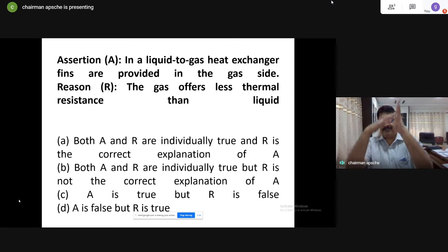When water is coming down from the top header to the bottom header vertically, horizontal airflow is expected, and the horizontal airflow moves across the tube surface. And here, those fins, if you have seen the radiator fins, are very closely packed. The gap between them is quite small, and therefore in all such cases gas flowability is very high.